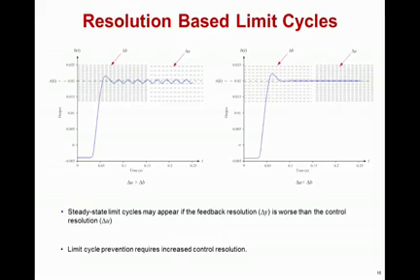In this example shown on the right, you can see that delta B, the change in the ADC resolution, is less than delta U, which means that the PWM resolution is actually higher. This allows you to have a more stable output because as the ADC measures the change in the output voltage, the PWM can more finely tune and control the output on the PWM stage, and therefore on the power stage controlling the output.